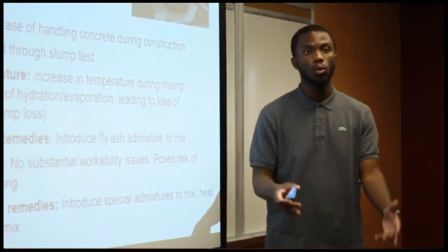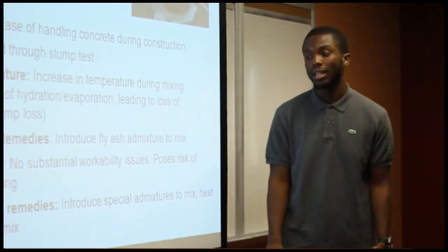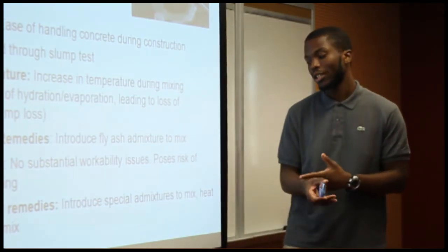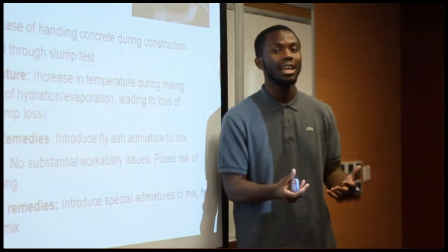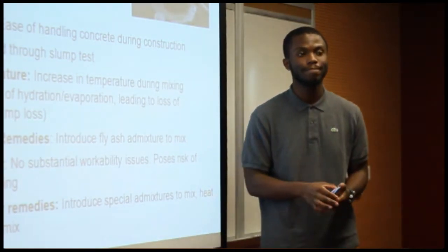So some remedies for cold weather mixing include introducing special admixtures to the mix or even heating the water that you're using in that concrete mix.